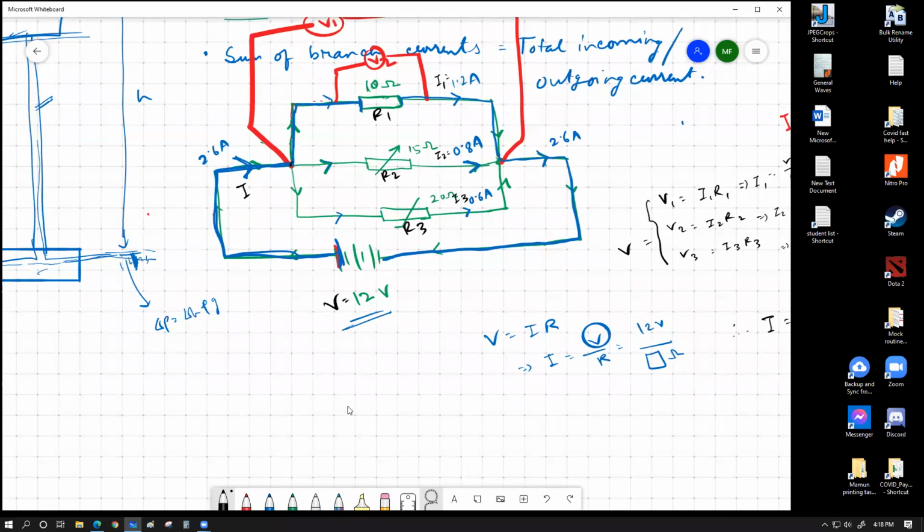An equivalent resistance is basically the idea that if all the components that we're considering for a certain part of a circuit, or for the whole circuit maybe, if the combination of all those resistors is replaced by a single value resistance such that the current flow remains the same, then that value resistor is called the equivalent resistance of the whole combination.